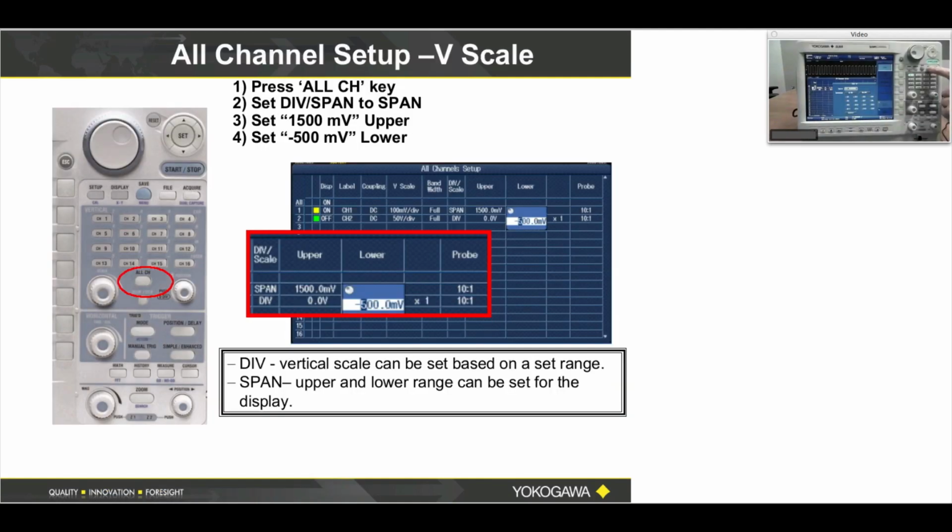So there are 2 ways to save a configuration. One way is to save it to a file which you can place on your USB thumb drive and archive it where no one can delete it, okay? So press File, and then Save Setup. Soft menu button number 2 where my fingertip is here.